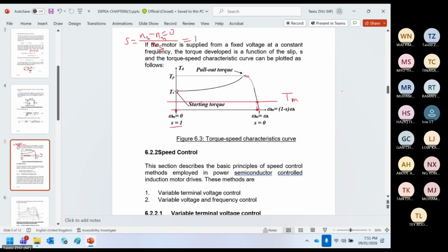So if your torque is a little bit bigger, so it's here, then the motor will slow down a little bit, but not that much. You see that the speed is very similar to this. Actually, my drawing is a little bit biased. The motor speed doesn't change much. So with the motor torque characteristic and the load torque demand, we can decide what the rotor speed is. The intersection is the rotor speed.